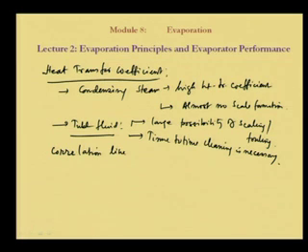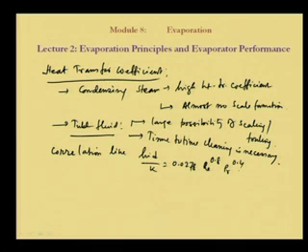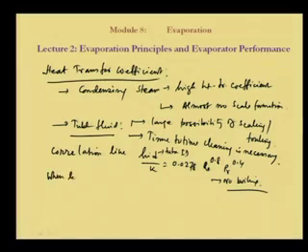like hD/k = 0.0278 Re^0.8. It is like the Sieder-Tate correlation, kind of, not exactly the Sieder-Tate relation, and this D is the tube diameter, tube inner diameter, tube ID. So, this correlation is used when there is no boiling, and when there is boiling, then we have discussed already in convective heat transfer that there are some correlations that can be used when boiling.